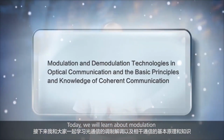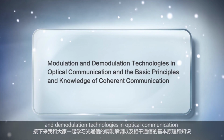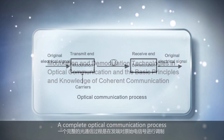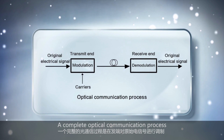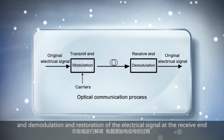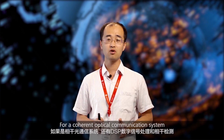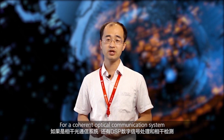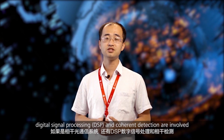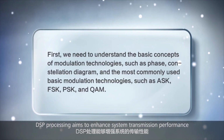Today we'll learn about modulation and demodulation technologies in optical communication and the basic principles and knowledge of coherent communication. A complete optical communication process involves modulation of the original electrical signal at the transmit end and demodulation and restoration of the electrical signal at the receive end. For a coherent optical communication system, digital signal processing and coherent detection are involved. DSP processing aims to enhance system transmission performance.